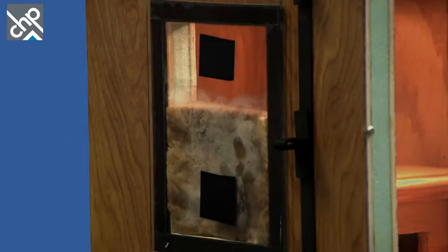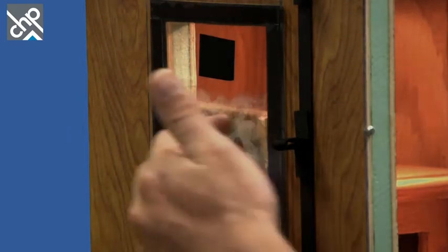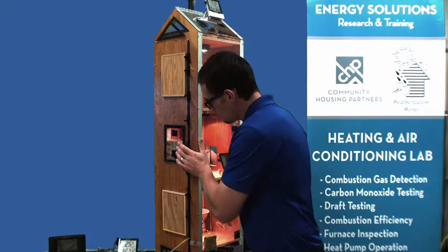So because we don't have a proper air barrier, and because we do have a vapor barrier on the exterior there, we've moved through, hit a condensing surface, and now we're just going to trap that moisture in that wall. So let's start moving around here.